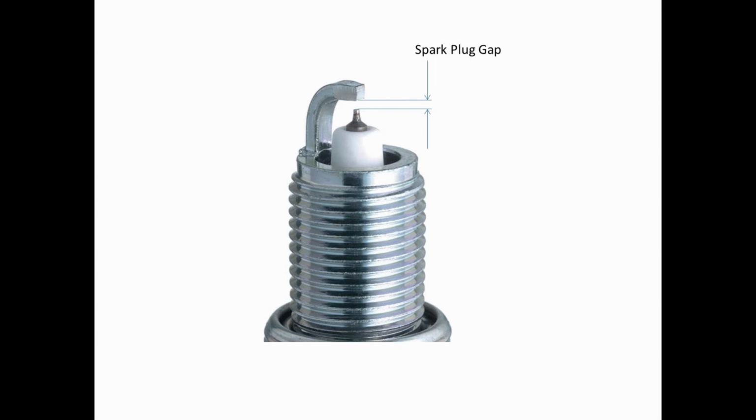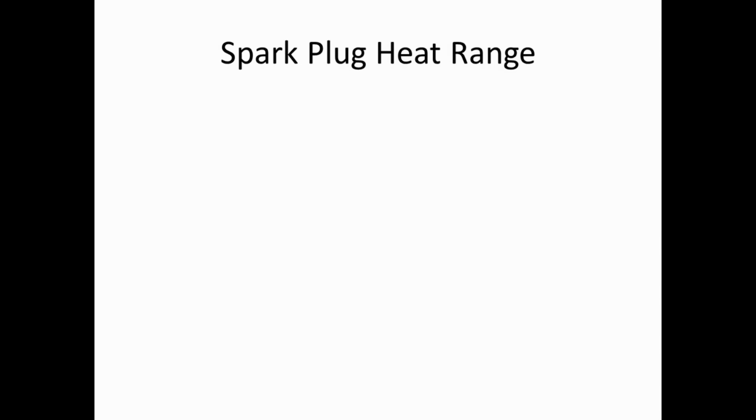If you have older plugs, you might want to tighten the gap up a bit. Again, don't do that with an iridium plug, but that is one way to extend your spark plug life a little bit. So the next thing about spark plugs is the heat range.